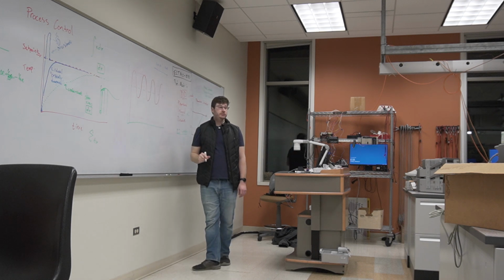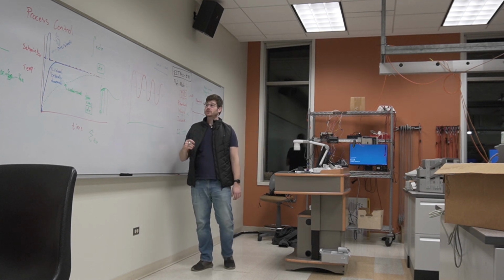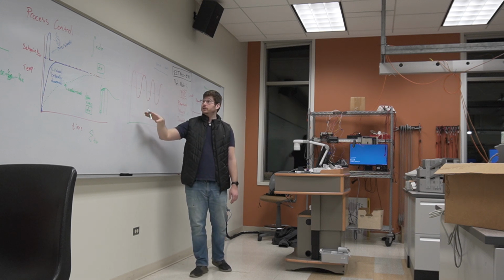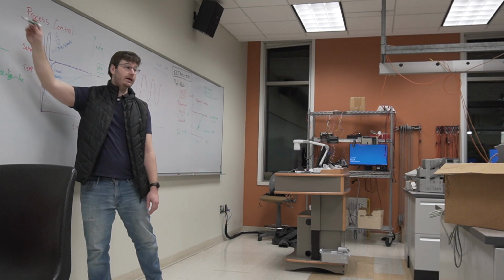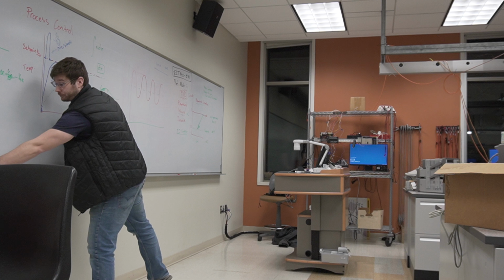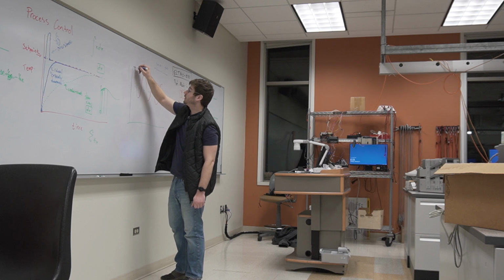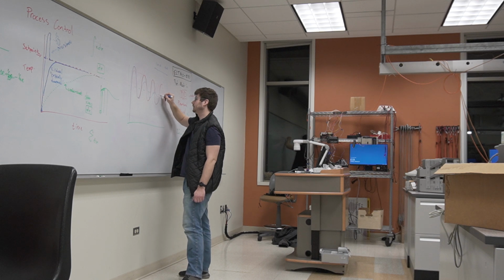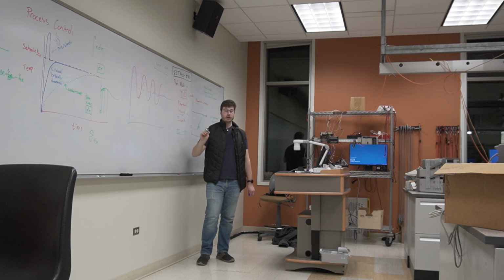So this is an oscillating system. This is also said to be an underdamped system, because ideally, it's okay if our process oscillates like this for a little while. An ideal PI controller actually will oscillate a little bit, but it'll settle down. The first one might overshoot a lot, but the next one will overshoot less and less until it finally settles in there. That's what you want more often than not. We call this ringing.